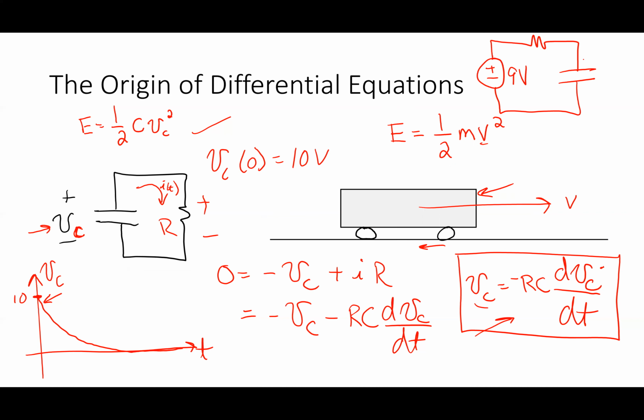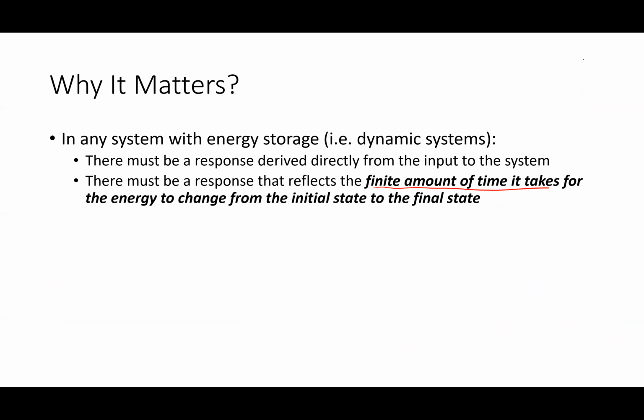What's the capacitor effectively doing? It's charging up, it's fighting back, basically. Because of the energy storage, it tries to keep its energy not constant, but continuous. So it fights back initially. A field is created inside of that capacitor to try to oppose the change. And because of that opposition to change, it takes a finite amount of time for the energy to change.